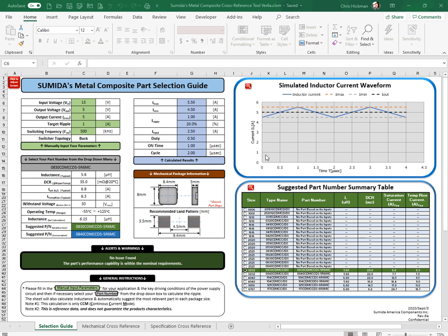It will then perform a calculation to establish a target inductance value. This inductance calculation is based upon a well-established industry standard methodology. The sheet will then use that reference inductance calculation to look through all available parts and recommend a possible inductor solution in every available size metal component inductor that fits the inductance and current requirements set above.